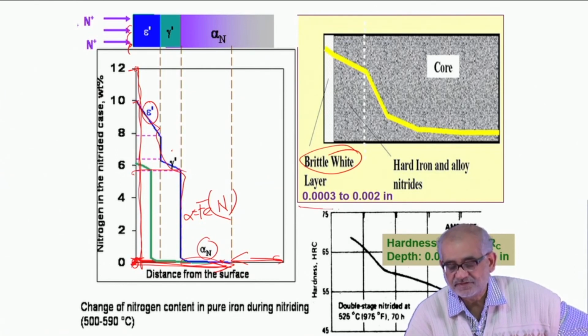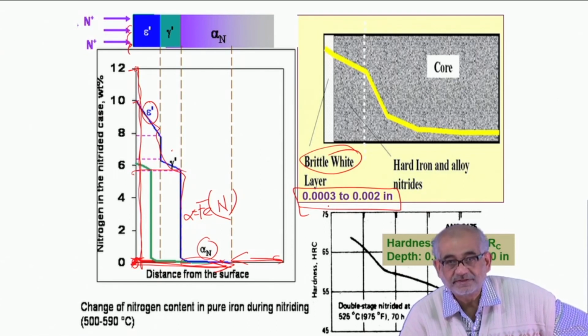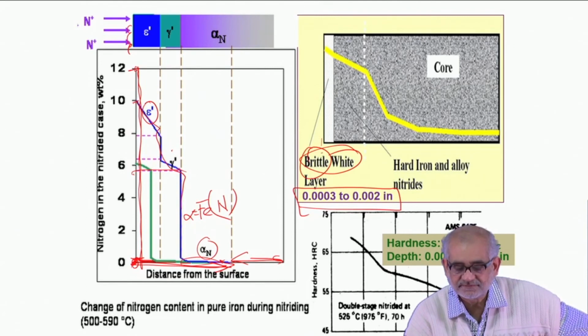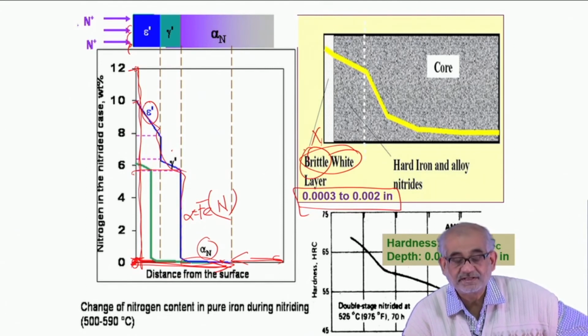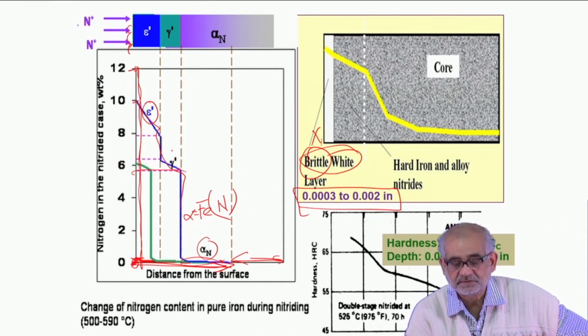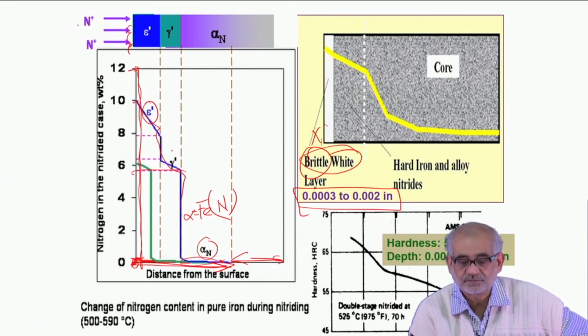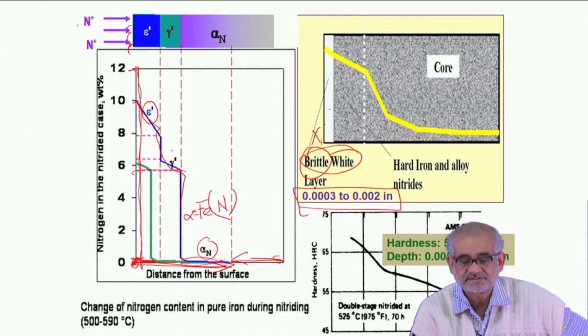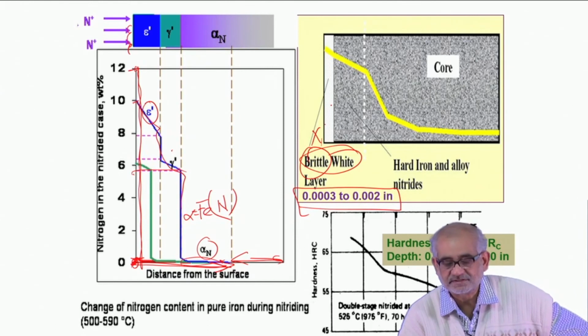Appears very attractive in terms of hardness or mechanical property, but actually is quite detrimental because this is highly brittle. So this brittle surface is actually no good for any further operation, particularly machining or further shaping. In fact, this surface being so hard, when it actually interacts with another surface which probably is not as hard as this, it certainly causes damage to the other surface.